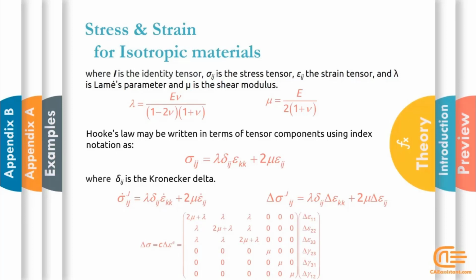It is very important to mention one point. As you can see, the Jacobian matrix is equal to the stiffness matrix. This has happened in this case and for the isotropic material, and this does not necessarily always happen for any type of material. Writing this relation and this matrix is your main job.